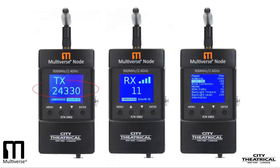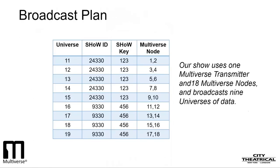That was a thorough trip through the Multiverse Transmitter and how we set it up for a 9-universe broadcast. At this point, if we configure some Multiverse nodes, we'll have a full working system. From the front screen of the node, or from RDM, we set the universe, show ID, and show key that we want. We'll assign 2 Multiverse nodes to each universe, giving us 18 nodes distributing our 9 universes. And that's our show, as we have set it up for this webinar. At this point, we're ready to hang and test our show.